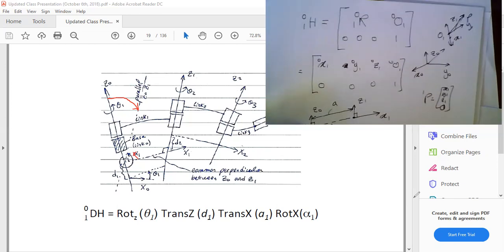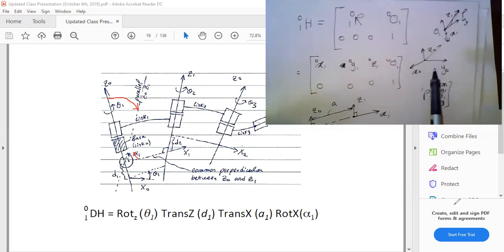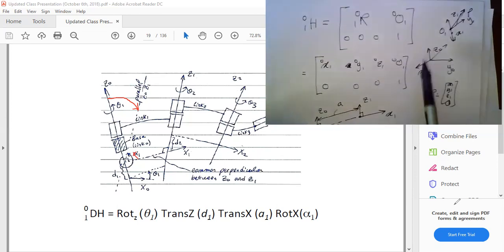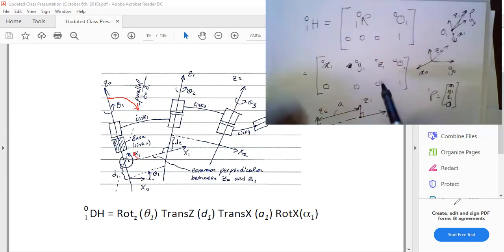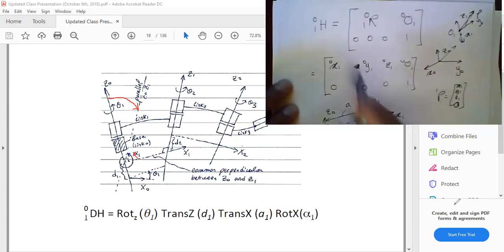we have two ways of doing transformations. You could make your own robot, and I'm sure many of you can do that. To do this, you have to write these vectors and get the values of x10, y10, z10. In reality, you don't need 12 values. Once you know x10 and y10, z10 is theoretically the cross product of x and y. So in reality, you need 9 values: any 2 vectors, and the third one is the cross product, and then finally O1.